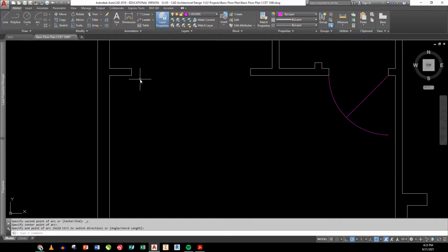Now, for the bifold door right here, you can get away with this. This is a 5/0 door. So I'm going to go out here at about 60 degrees, and I'm going to cut that in half. That means this goes 15 inches, and then it goes back down at the opposite 60 degrees for 15 inches. Once I do that on one side, I can go copy by CP, grab this by its own endpoint right here, and move it over there.